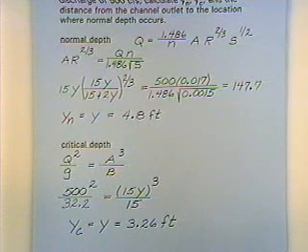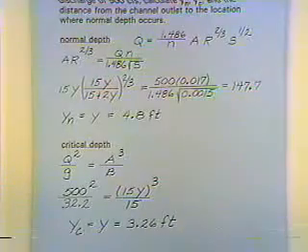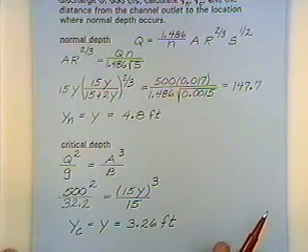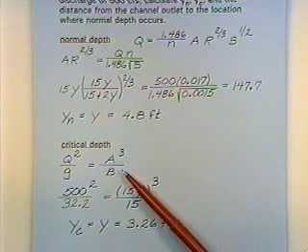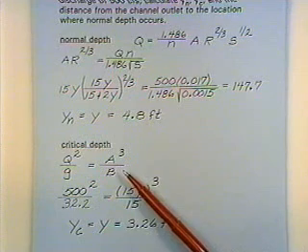That's the depth that the water would be flowing at if it hadn't been for the backwater effects of that 10-foot deep river. And so we need to know what type of flow condition we've got, and knowing the critical depth allows us to figure that out. Here's our critical depth equation we've used in the previous example. I've reproduced the equation which we derived a few minutes ago.